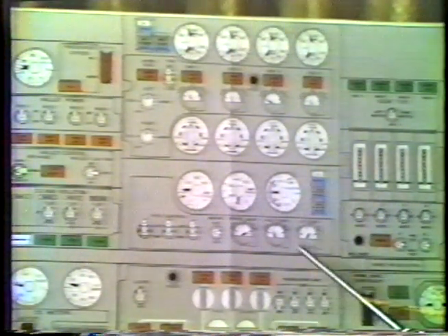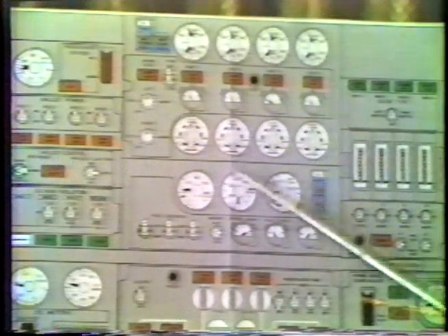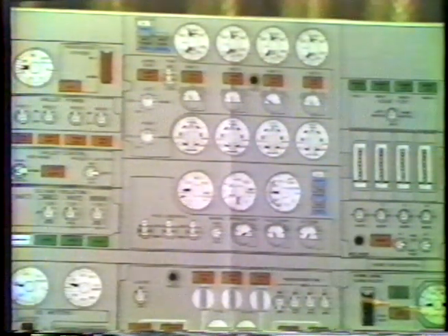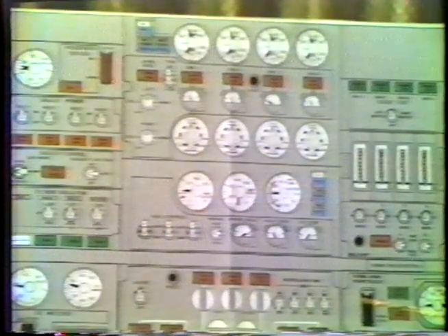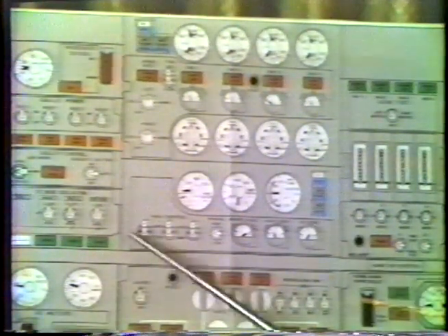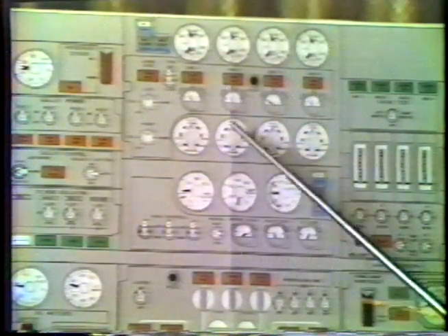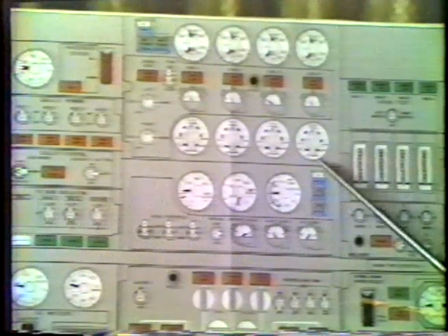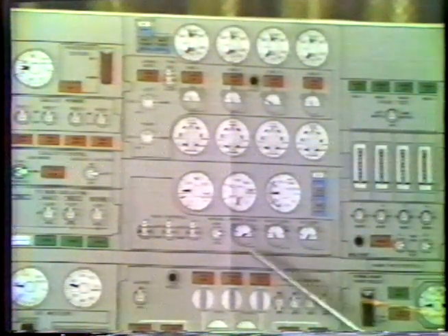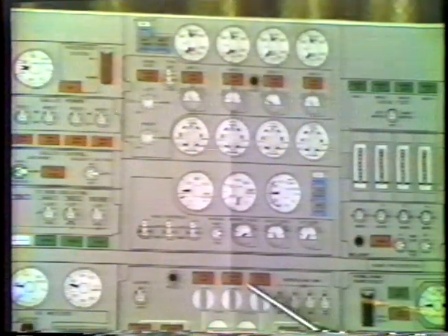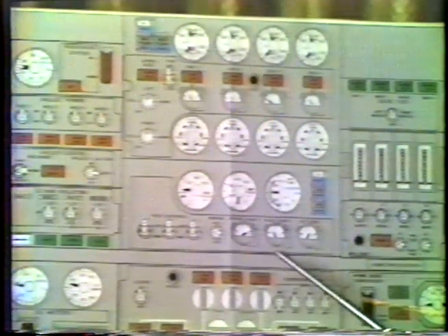The full cold mode will run the pack to 35 degrees. Now, you can override that by going to manual, but if the occasion arises where all 4 temperature controllers are in manual, the packs will go to the full cold range because they have no input control temperature.